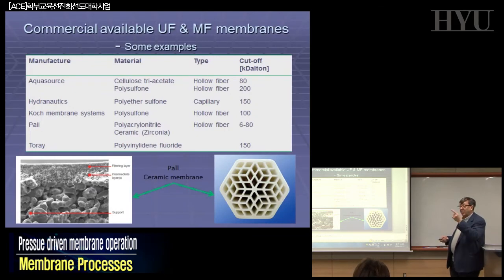That means before starting, if you want to do research on new ultrafiltration membranes, check what already exists, because this is an area that is well covered, and there are membranes which can be inorganic, ceramic of any kind, or polymeric, and you can see here they are nicely asymmetric. The real membrane is the top skin here. This is about 300 microns. This will be 10 microns, no more than this.